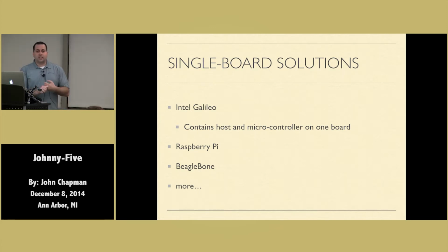You can also do programs on Raspberry Pis and BeagleBones, right? So instead of doing Firmata-based communication, you can actually do GPIO communication, which will work on those platforms. You will have certain limitations, like I2C compatibility is not really there. One that's kind of tough is that things like servo motors can be troublesome on those platforms. So if you look at those platforms and let's say you're just doing LED control, they're very simple to do on those platforms. So depending on your usage, they may make sense to use. And as we went through in the beginning, there's also a lot of other choices for I/O options.